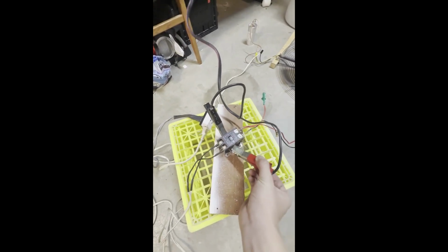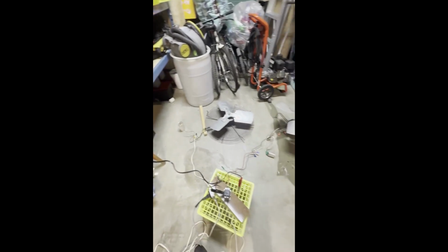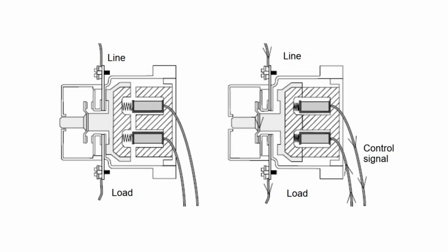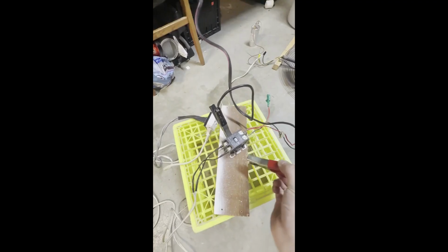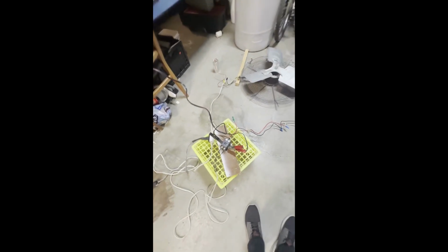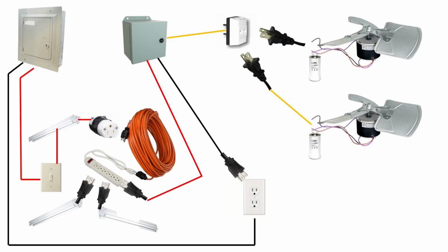You see the contactor and the battery charger I was using to power it? Well, that part was for show more than anything else, since it had no effect on anything after I had hooked it up. For those who don't know, a contactor is an electromagnetic switch. At the bottom, there is a coil which, when energized, turns into an electromagnet, which sucks in the contacts and closes the circuit. Since the power to the contactor coil was never lost during the experiment, we can just ignore that any of it existed. It might as well be directly wired like I had originally planned.